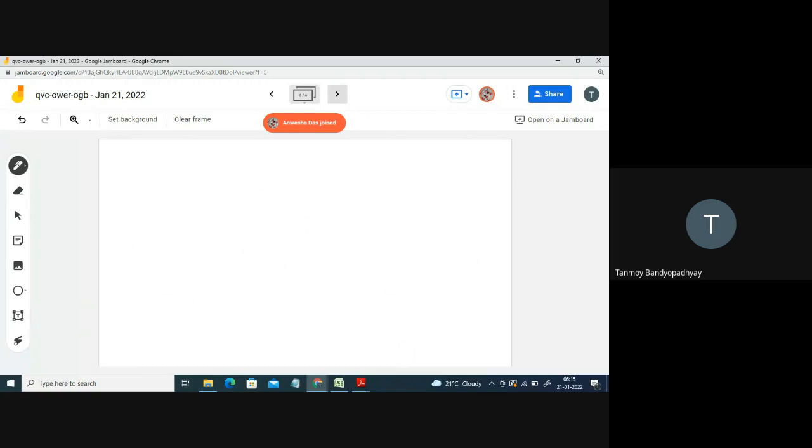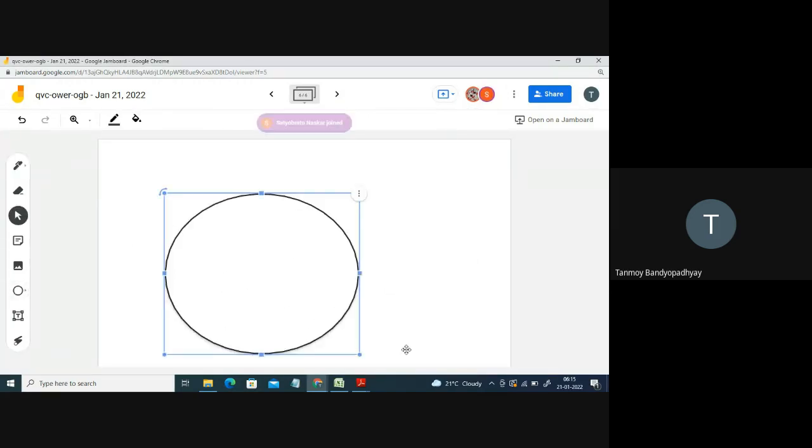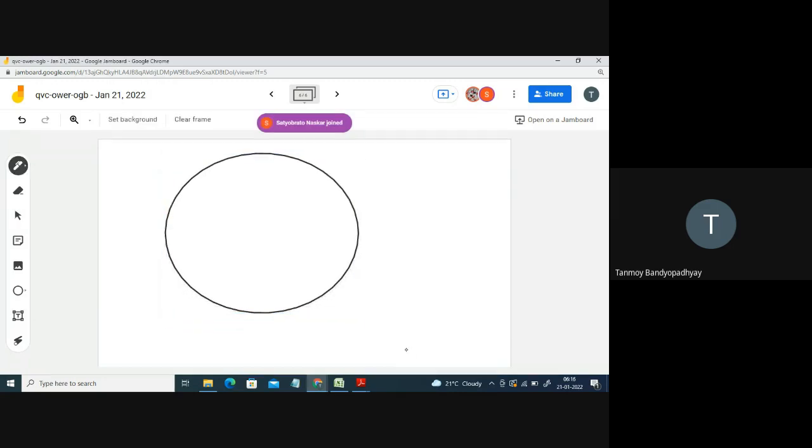I am just repeating that here. This is the circle, this was the circle. This is the point B. From this point the force RA passes. So this is the line of action of the RA force. What I am doing is extending RA. RA will have two components. What are the components of RA? This is one component, and this is actually RA. This is 30 degree. So this is RA cos 30 degree, and here you will have RA sin 30 degree.